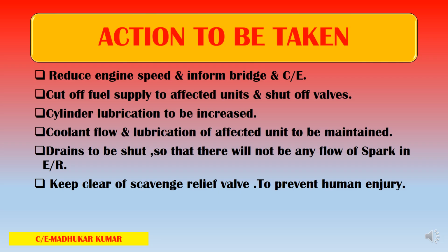Precautionary measure. Once you have checked and identified, there is no need to open the drains. It has to be shut. Keep clear of the scavenge relief valves to prevent human injury, because if the pressure inside the scavenge space increases, the scavenge relief valve will lift, and if any person is standing nearby, they can get injured. So we have to avoid it.